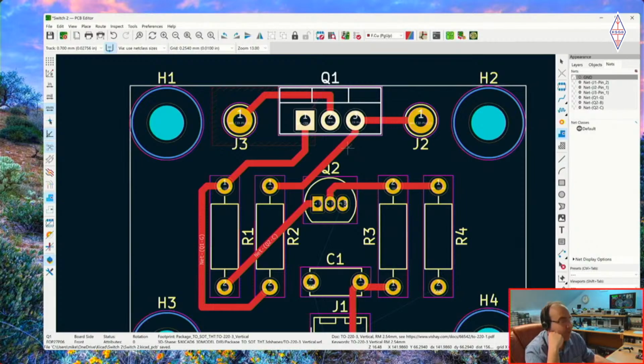Actually, I just did that wrong. Let's just edit that a second. That's a great way to show that you can undo things. I've just selected it again because I actually wanted it not to go to there, but to go to there. And I seem to have ended up with an extra corner, which I will take out. You can just click on these corners and move them up and down. So that's going to be a big area of copper on the board.